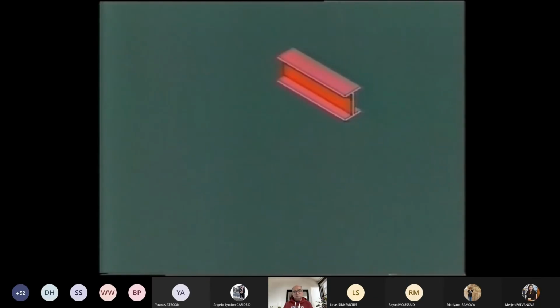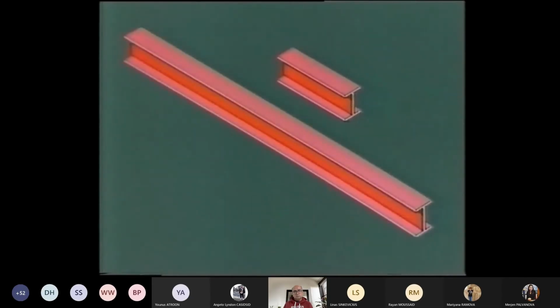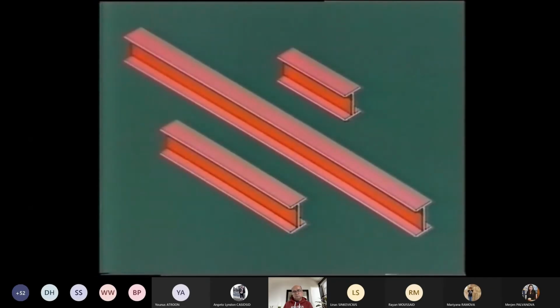For a very stocky beam, the plastic moment is significantly less than the critical moment and instability does not occur. For a very slender beam, the reverse is true and the beam will fail by elastic instability. The response of very stocky and very slender beams is quite clearly defined and relatively simple to analyze, at least in an approximate manner. However, many practical unrestrained beams lie in the intermediate slenderness range, where the effects of elastic instability and plasticity interact.